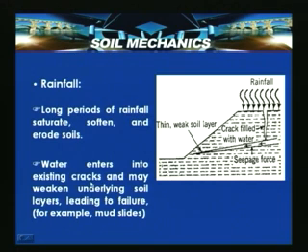So, in the picture shown here, this is the continuous rainfall with a certain rainfall intensity, and this is an already existing crack. So, water enters through this crack, enters a weak layer and induces a seepage force, and because of this the crack filled with water induces a water pressure. Then this water entering the weak soil layer tries to lubricate this particular surface and makes the entire soil mass an unstable mass.